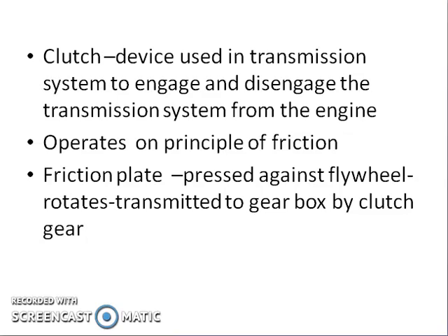In certain cases where we have to change the gear from high to low or from low to high gear, if the transmission system is not disengaged, there may be a clash in the gears and gear teeth failures may occur. And during starting, if the entire transmission system is attached to the engine, the starting torque required will be very high and the starting motor will find it difficult to start.